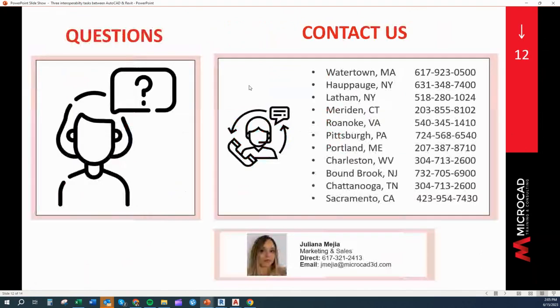Having said that, to sum up, it's quite common practice to work with CAD files as many firms are still using CAD software. It is important to understand and set the workflow to coordinate with them and maintain the good quality and health of your models. However, combining CAD and BIM will affect performance due to the limitations and constraints in Revit. Always make sure to audit and link the CAD file. Nothing more, thank you so much for joining us.